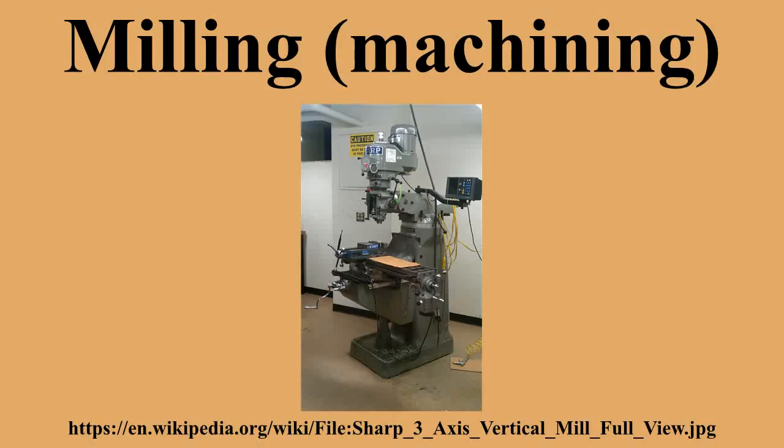Equipment. Milling is performed with a milling cutter in various forms, held in a collet or similar, which, in turn, is held in the spindle of a milling machine. Types and nomenclature. Mill orientation is the primary classification for milling machines. The two basic configurations are vertical and horizontal. However, there are alternative classifications according to method of control, size, purpose and power source.